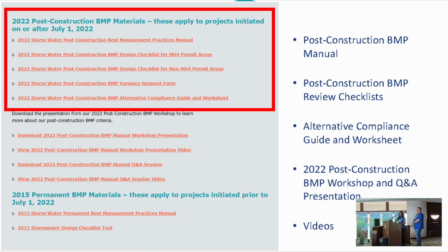If the project is going to generate a deficit, the designer shall submit a variance request. And DOT has to approve that, like, the designer has exhausted all the options to implement LID, treatment control, and manufactured treatment devices. So, like, nothing is feasible, or whatever partial credit is actually justified.